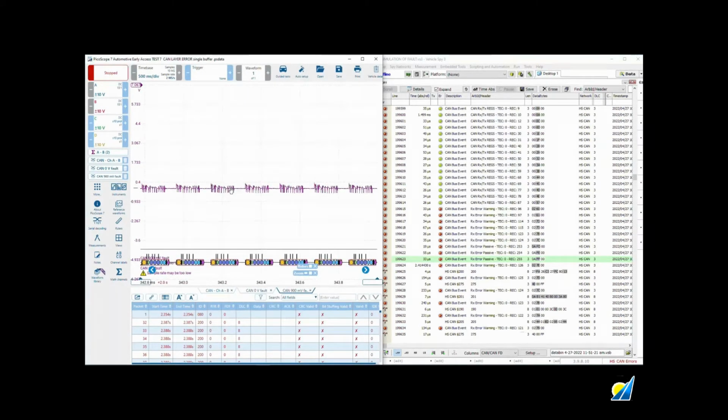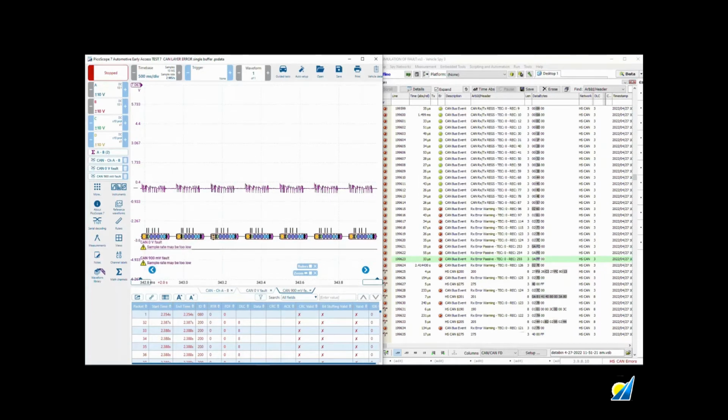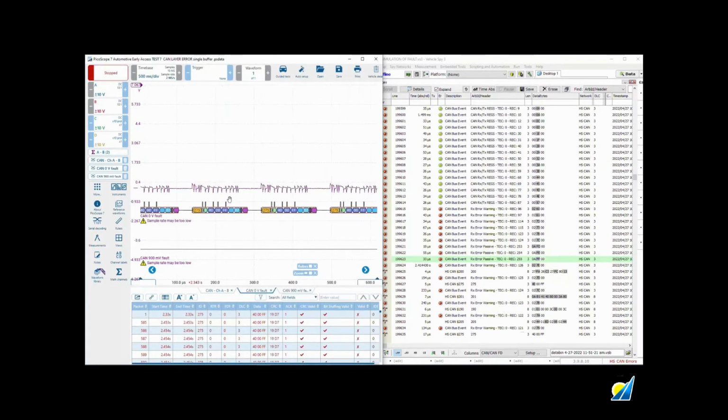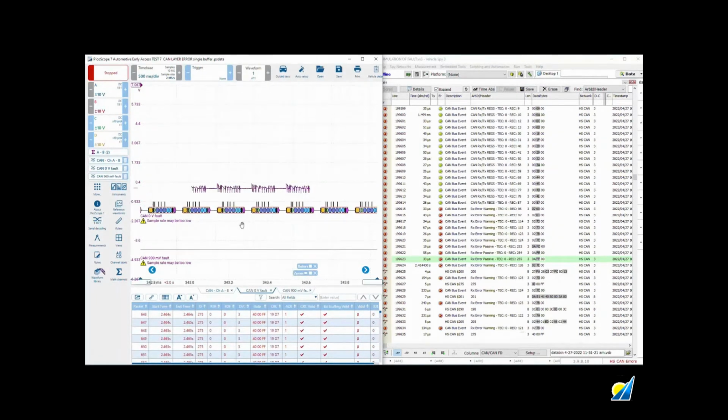And I have decoding on it. Now this one here is 0 fault. So I've used 0 as my crossing point in the decoder. And if we keep zooming in, it reveals ID 275. ID 275 appears to keep transmitting through that fault condition.